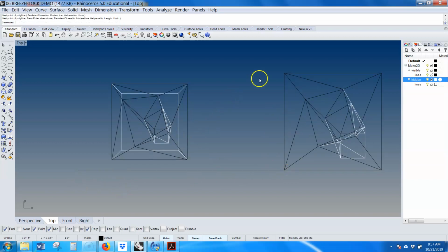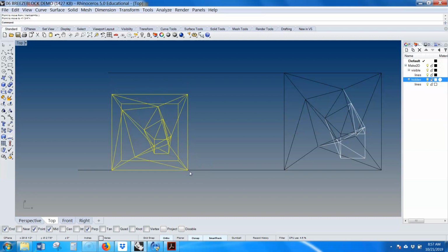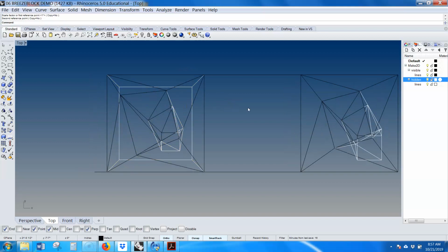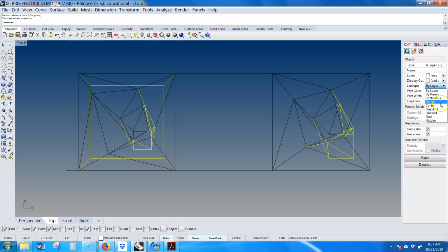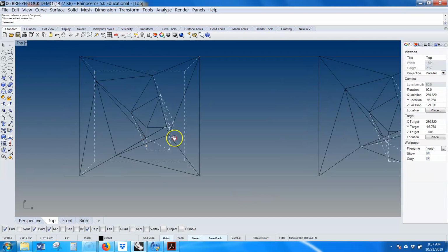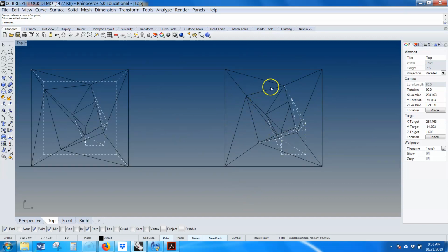So this is why you might want to line them up side by side and actually cut the section lines through before you do the perspective, just to make sure that it's all the same scale. We can always just stretch this back. It shrank, but where do you actually make 12 inches? This is the top, or do you do the back? And if we do the hidden lines, we should be able to make these dashed. See that? There you can see the depth of this thing compared to this. Here you're seeing the opening through the middle, but here you're seeing the perspective of the entire block plus the opening through the middle.